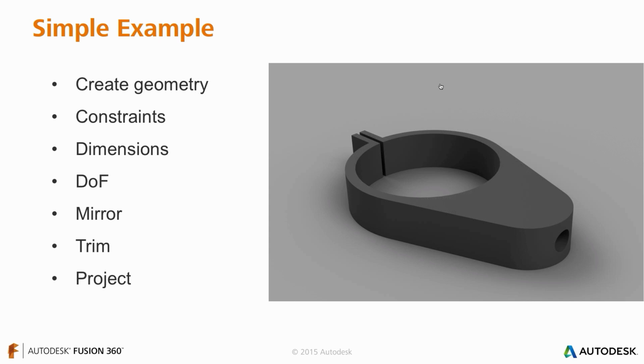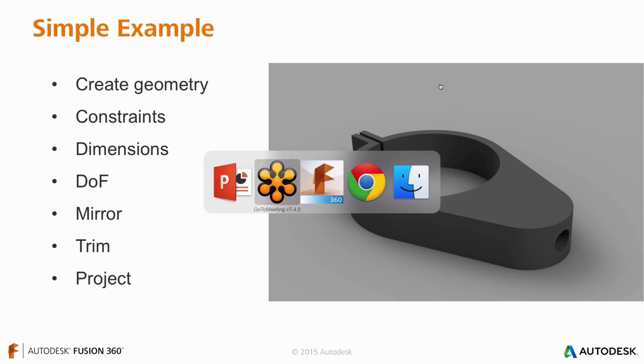And I actually put them in this order because this is typically the order that we're going to be problem solving in the sketch workspace inside of Fusion. You're typically going to be drawing your sketch geometry, then using constraints to eliminate degrees of freedom and really make sure that the sketch geometry will adapt in the way that you expect. And then finally use dimensions to lock in those values that you have, maybe for sizes or distances or something like that. And it's important that you properly constrain everything ahead of time so that when you add a dimension, it behaves the way that you expect.